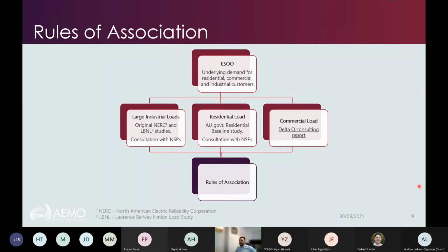Obviously, keep in mind that between, say, a very old mine site and a very new mine site, you're going to have a very different makeup of end-use loads, largely inverter driven for a newer mine site. Only when a motor gets replaced may you consider a VSD, or if there are financial incentives to add a VSD, then you go down the VSD route.